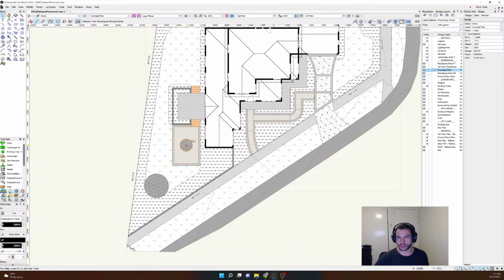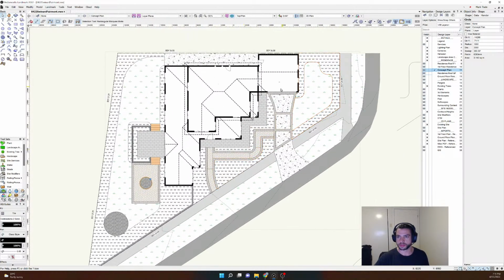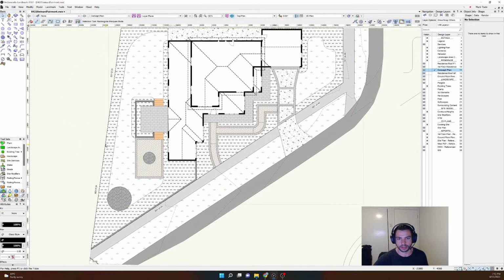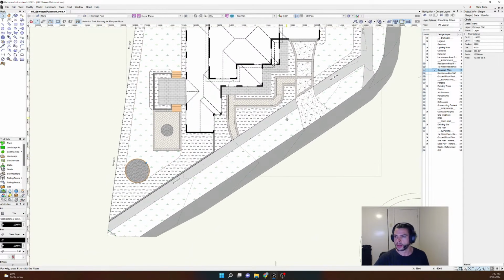So you can see all this is just line drawings. I started out with a sketch plan and then put that in here as polyline drawings. This design may change entirely throughout the process as well, and that's the beauty of Vectorworks, is you can edit the design after you've done it in 3D. You don't need to show the 3D. Draw the 2D, then do the 3D, and then change the 2D and change the 3D. It's all linked together. So hopefully I can give some examples of that as we go.